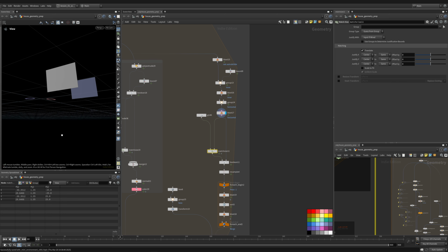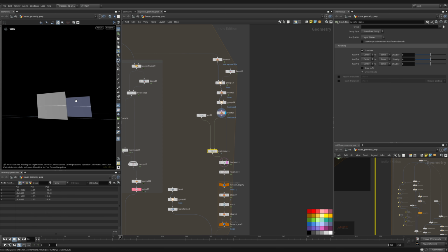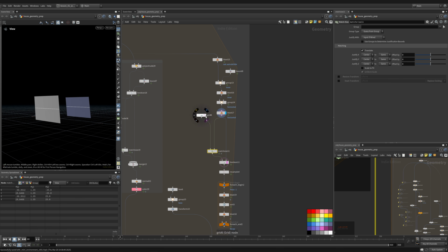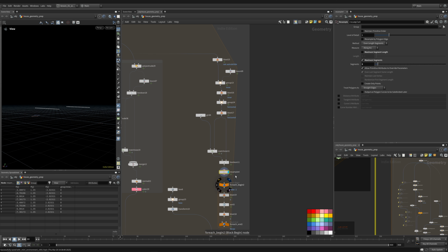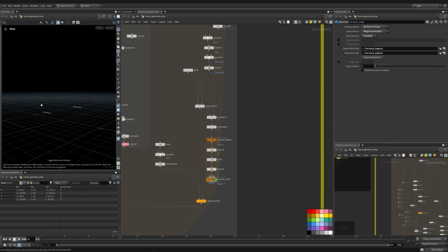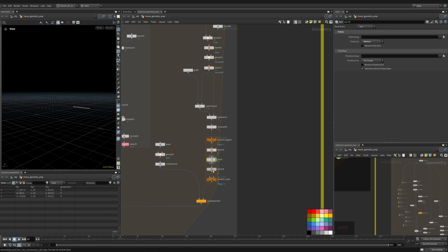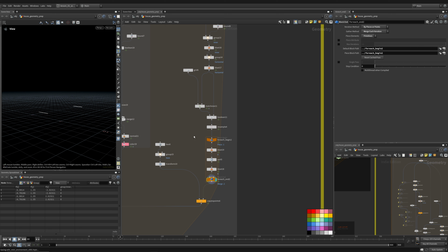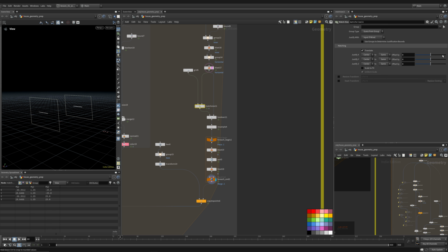So we want to figure out now how to get, it looks like we want a line. So I'll do a grid, match size to place it in the middle, Boolean, resample. Same way we did the windows, and I'm going to use this one, blast, sort, blast, and then this. And the reason I did this area, I'll show you really quickly. First, this match size, I could offset the window height if I wanted to by that justify Y. So that's one thing to know.